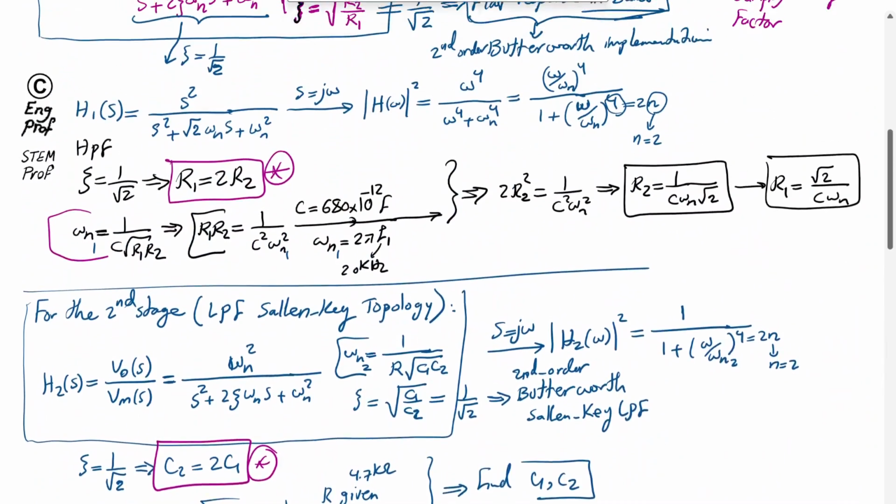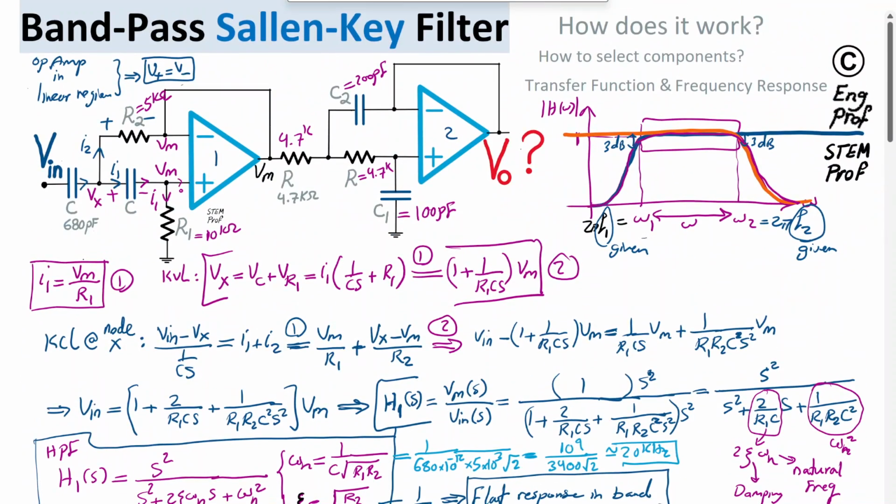I hope that this example is helpful in illustrating how there are many ways to design a bandpass filter. This is not the only way, but the nice thing about this method is the flexibility it brings. If we use, for example, 2 op-amps from the same package, from Analog Devices or Texas Instruments, which offer dual or even quad op-amp packages, the op-amps inside one package are matched very well.